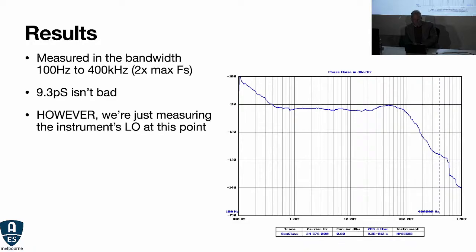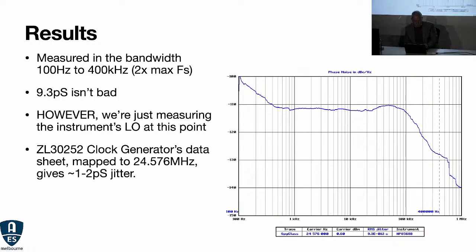But we're just measuring the instrument at this point. And I know this because the 252, just based on the data sheet, at 24,576 should be in the 1 to 2 picosecond range. So we're measuring something way below the noise floor of the instrument.